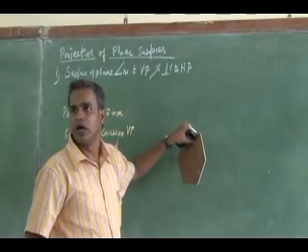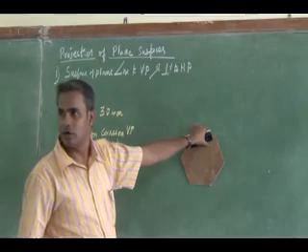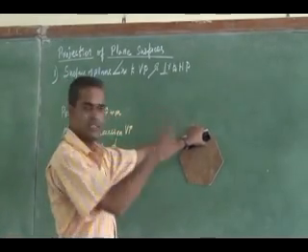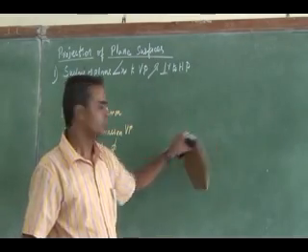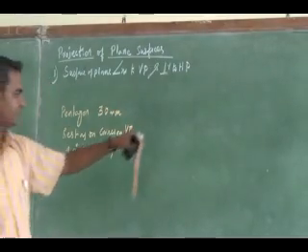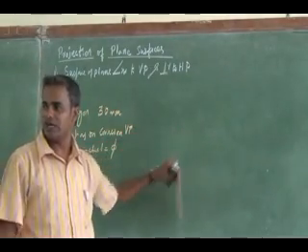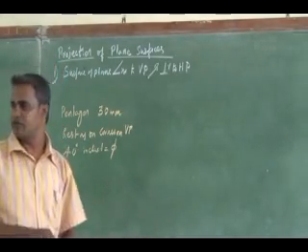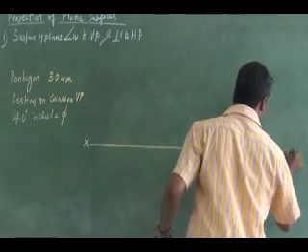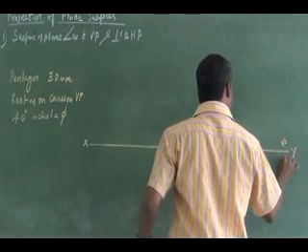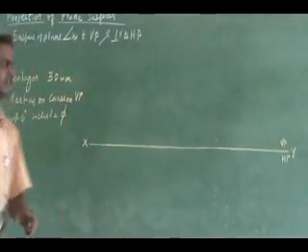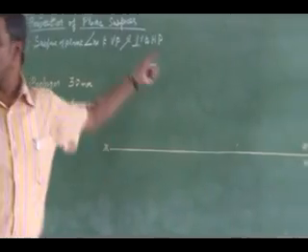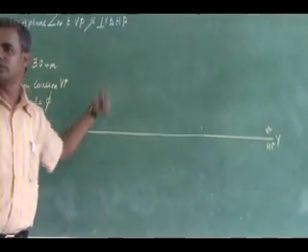So what do I have to do? I have to make it aligned to the vertical plane. That is the first step. I can see the true shape and I can get the final top view length. After that I have to tilt it. The top view length has to be tilted to 40 degrees. Then I can obtain my final front view. The first assumption I am making is parallel, so that since it is resting on VP, I can see the front view true shape on VP, where I have to draw the true shape for this.